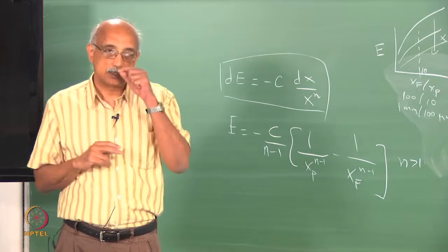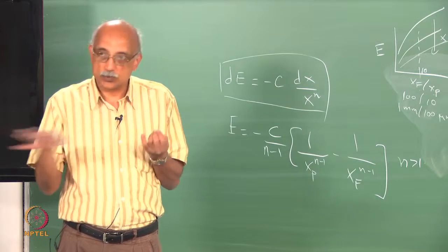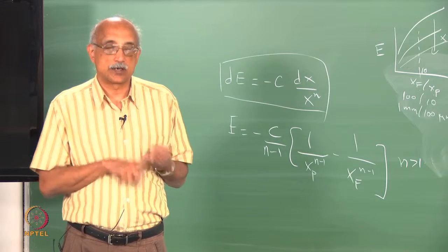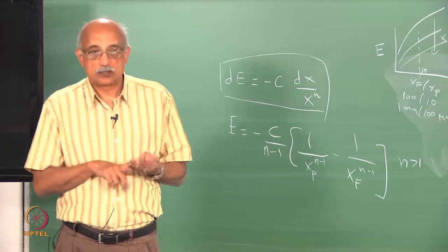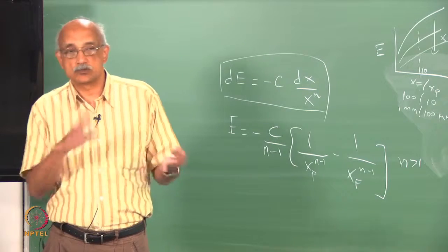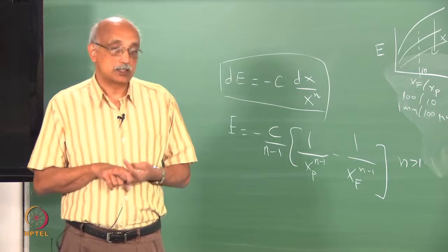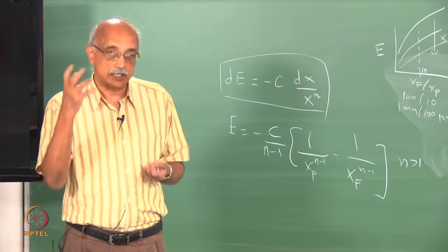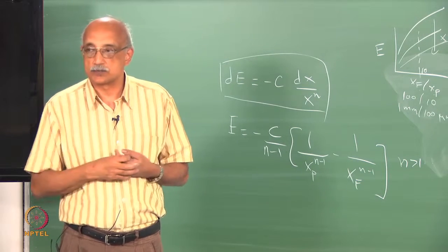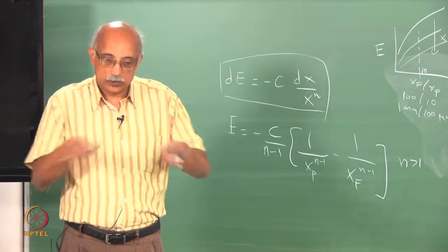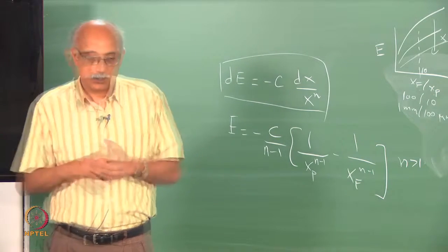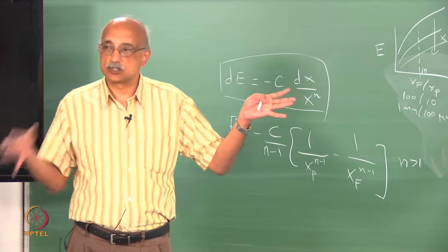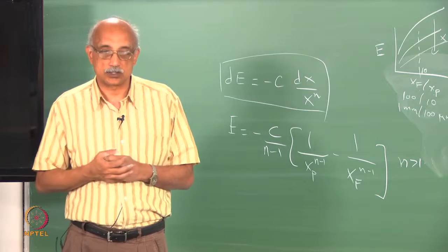So, there is a lot of interest in industry in using a sequence: crushers for reducing large particles to smaller sizes, grinders to reduce them further, followed by ultrafine grinders, and finally something like a cavitational size reducer, which will take it down from micron sizes to sub-micron sizes. So, you have to look at this whole thing as a system to go from your feed size to the ultimate product size that you are interested in.